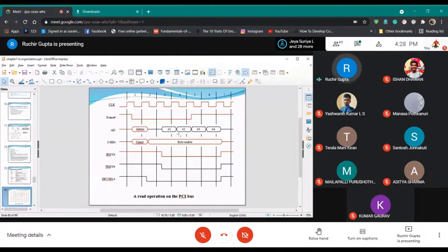And this is the command, and once the byte enable comes, now you can see that your bytes are coming. And of course, initiator ready and target ready signals are a must. If they are not there, no transaction can happen. And of course, which device is being selected has to come. I'll talk about DEVSEL in some time. So this way, the transaction happens.